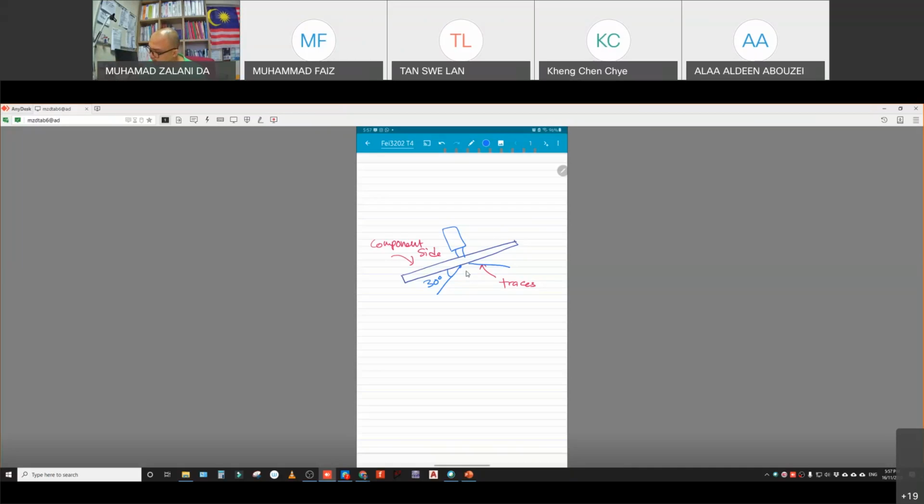Not to bend it too close to the surface of the bottom, something like this. So this is not good, because at least we want to allow some space to do the soldering of the pad. We have the copper pad.